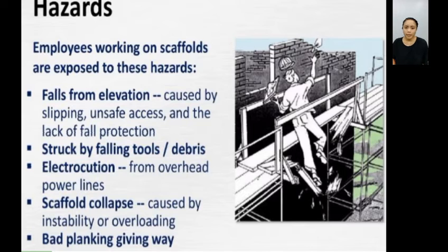What are the requirements for scaffold planking? Scaffold planking must be able to support without failure its own weight and at least 4 times the intended load. Solid sawn wood, fabricated planks, and fabricated platforms may be used as scaffold planks following the recommendation by the manufacturer or a lumber grading association or inspection agency.